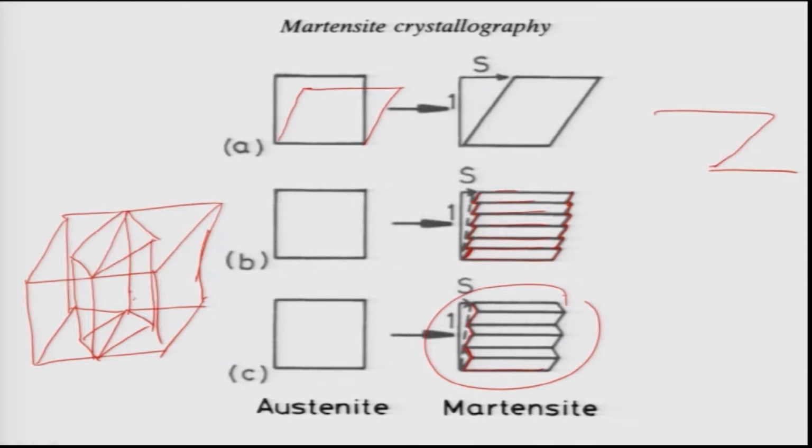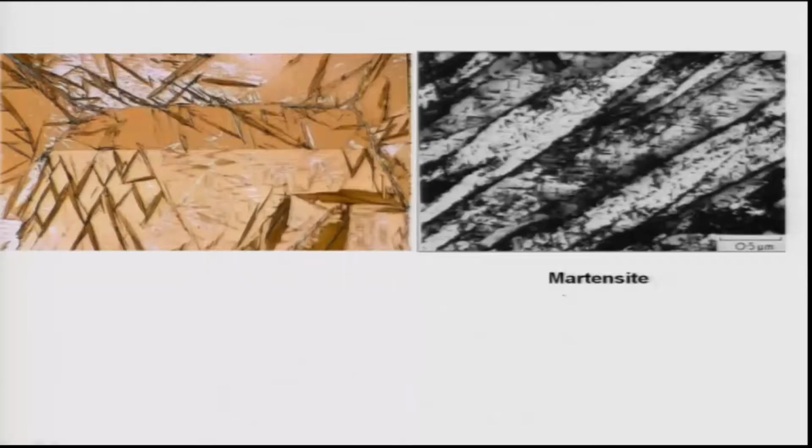As you have seen, when you look at martensites in steels, in many cases you will be confused with bainitic plates, because bainite and martensitic plates look almost similar, especially lower bainites. But in martensite there is no carbide phase. Let us be clear about it.